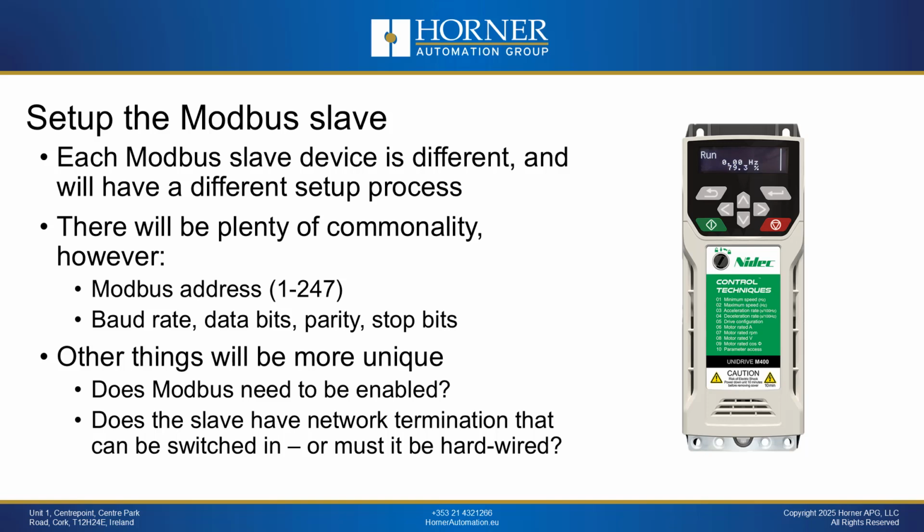Now normally, our recommendation is to use the default settings on the slave if at all possible and adapt your master to adjust to the data rate of the slave. That is typically easier to do.